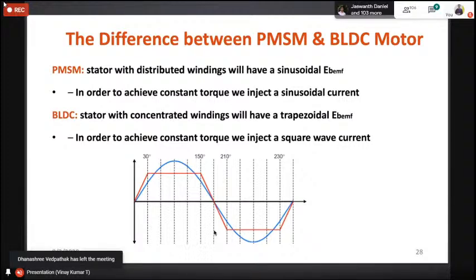For high power applications, non-sinusoidal current with high magnitudes will damage other electronic circuits. Heat dissipation is also more in BLDC machine compared to PMSM drive. So that's why in electric vehicle application, generally electric drives application, they will select PMSM. BLDC only for low power application.